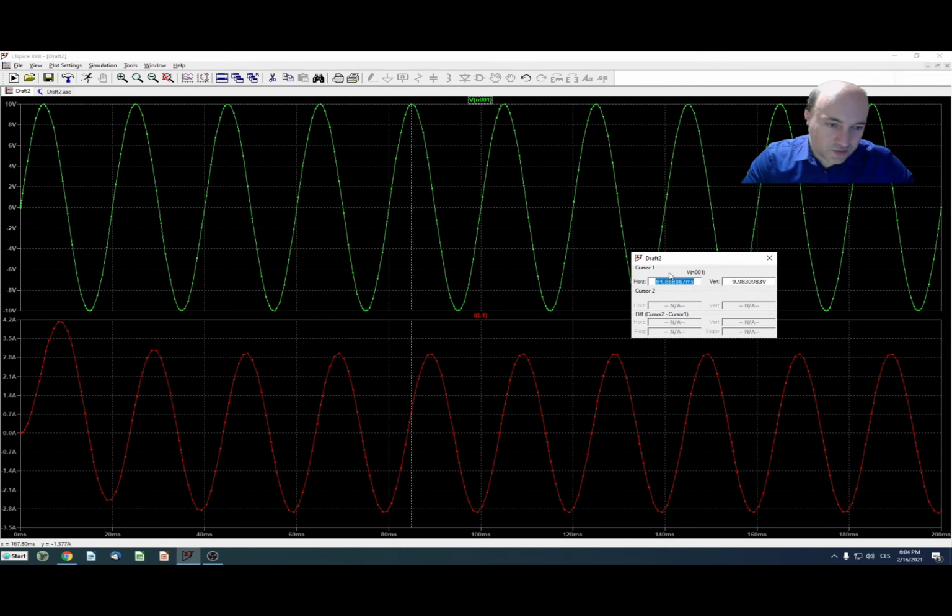In the window that we have in this part, we can see the amplitude and we can see the time shift, and here on the bottom we can again click on this chart, and I could now read my time here when I had 84.86 milliseconds, and I can drag it to my peak here, and I have some other time. So from the time difference I could calculate the phase shift.